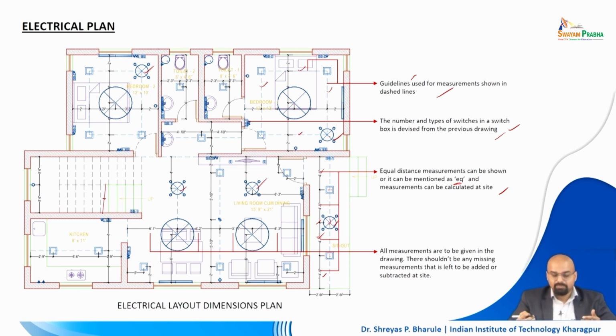Often sometimes what happens is, if in the design process the drawings are not being updated, and because of unavailability of a certain appliance or a certain fitting, you go to some other brand. Because the drawing was created considering one particular brand, and that brand is not being used, the sizes of the same fitting or fixture may change.